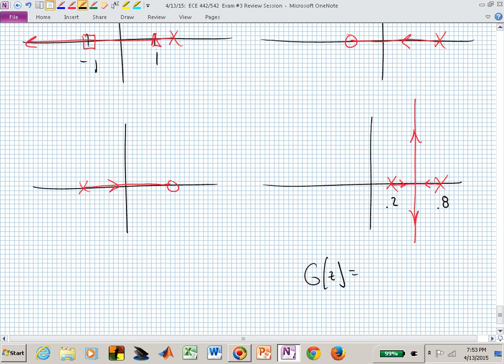Let's say that the numerator is 1, so that I now have z minus 0.2, that's my transfer function that I'm going to put into a negative unity output configuration. Can you find the gain k, the upper bound on k for stability? What's the lower bound? 0. You have an open loop stable system.